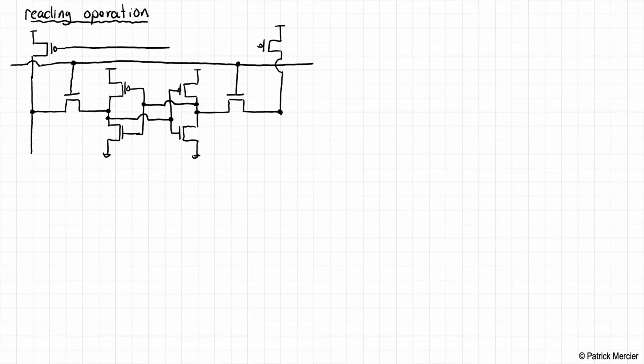And the entire bit line is pre-charged to a specific value, in this case, VDD. This pre-charge is activated by a clock called phi2 bar. Okay, so let me make a little annotation here. And in the pursuit of saving space, I made things a little bit too compressed, but I think it'll work out.